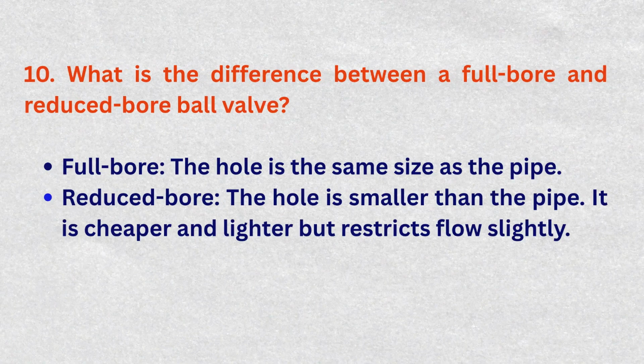What is the difference between a full-bore and reduced-bore ball valve? Full-bore, the hole is the same size as the pipe. Reduced bore, the hole is smaller than the pipe. It is cheaper and lighter but restricts flow slightly.